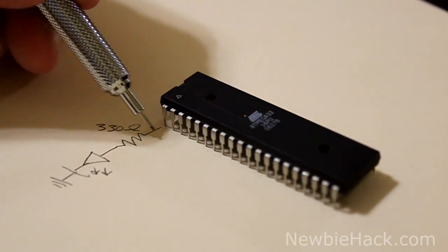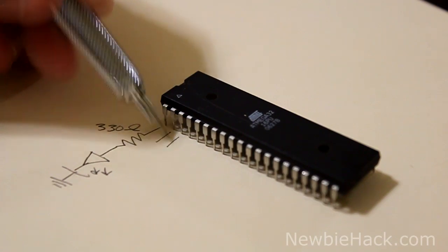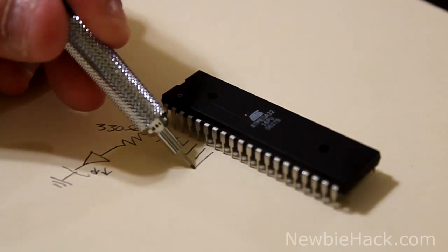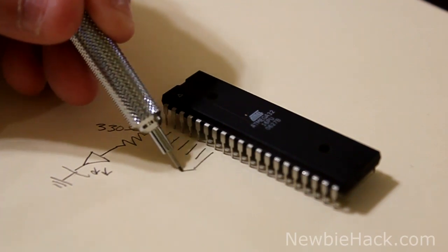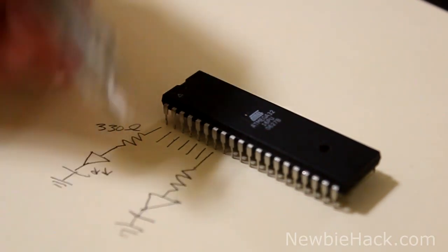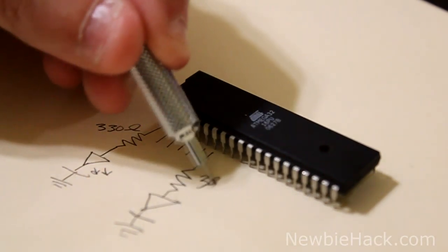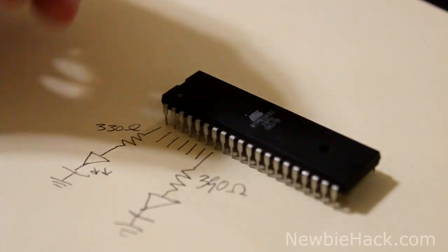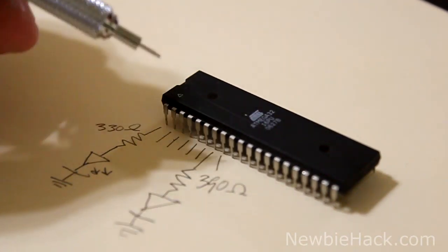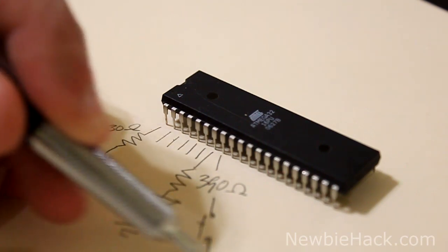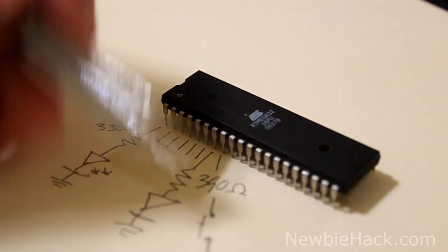We're going to repeat this same on all of these pins, 1, 2, 3, 4, 5, 6, and 7. But the 7th one actually is a little bit different because we have a red LED at the end, and I'm using 390 ohms of resistance. On the 8th pin, which is right here, we're going to put our button, as we did before. We are doing software debouncing, so we're not going to use a capacitor.